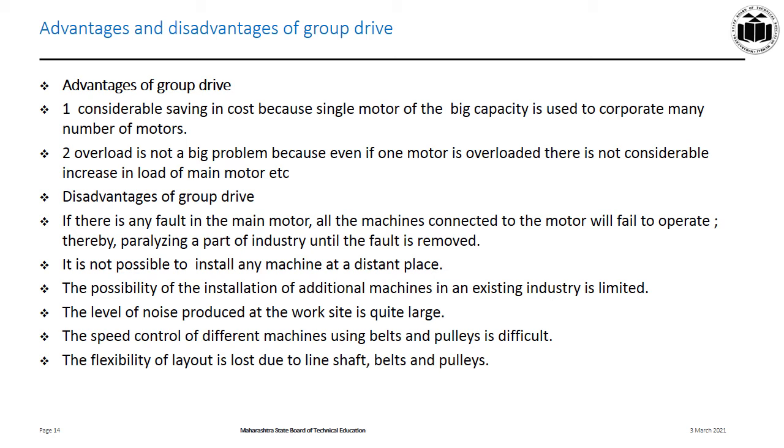It is not possible to install any machine at a distant place because there is an arrangement of the belt. The possibility of installing an additional machine in an existing industry is limited, which is also not easily possible. The level of noise produced at the work site is more. Why? More systems are working together, and speed control is also a big problem.